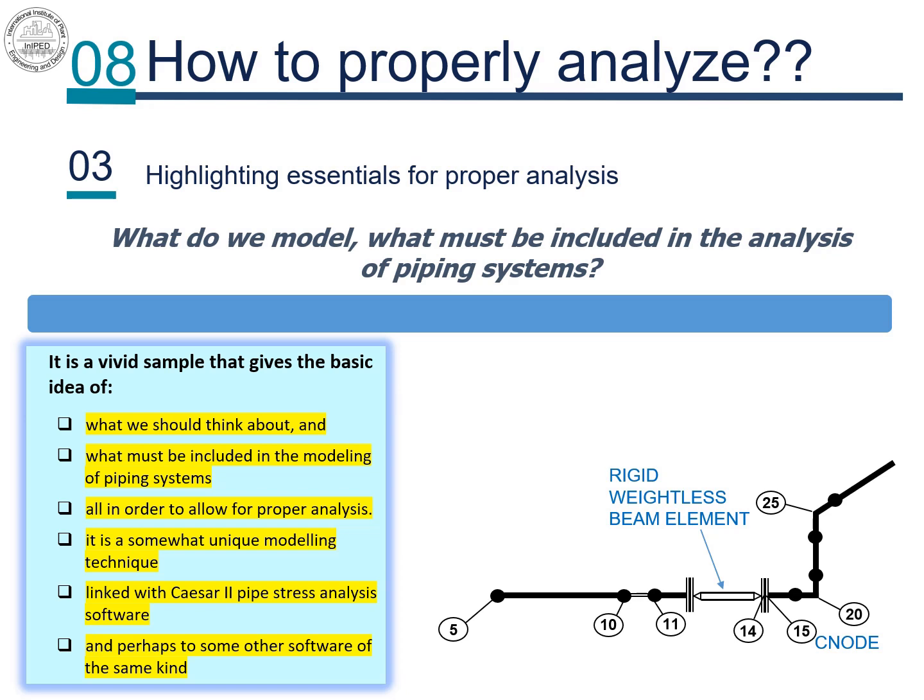Connecting nodes, C-nodes, can be used to tie one node of the piping system to any other node. This tying can be associated with nodal degrees of freedom and optional defined stiffnesses. So with this technique, any type of tie-ins between 2 nodes can be defined, and this allows for simulating in the model anything that the stress analyst would find necessary. Combine this with the possibility to use rigid or flexible, weightless or not, elements for the beams to form the structure, and the combinations of what can be modeled are endless.